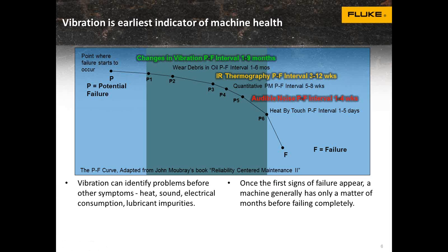When I was in the Navy, we were tracking faults in rotating machinery 12 to 18 months down the road. We could watch bearings and looseness and imbalance on machines go from slight to moderate, stay at moderate for months, or even a year, and then you would see the machine go into serious and extreme, and we knew the machine had days left, and we'd take it down and fix it. So that's an important part of vibration, is knowing when to take a machine down and when it's okay to let it run.